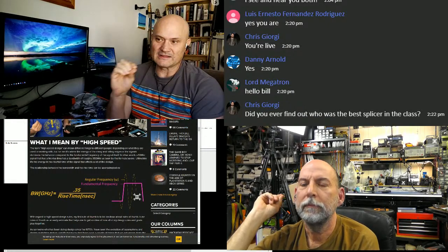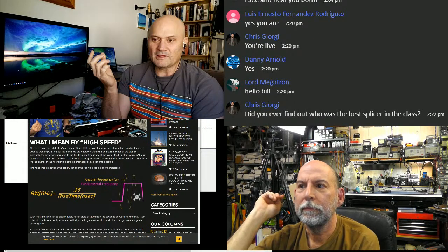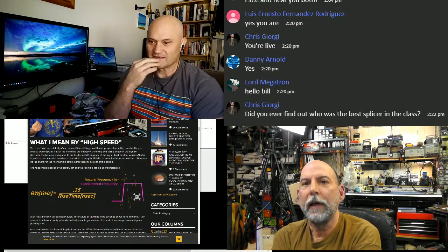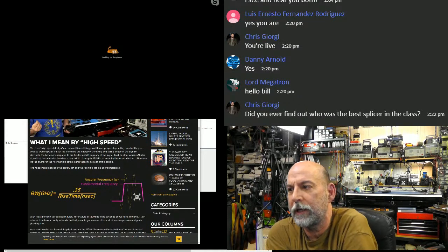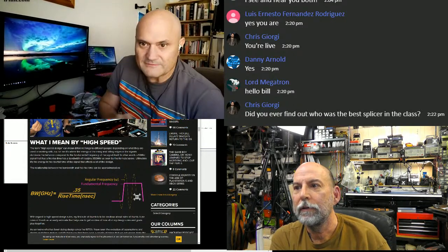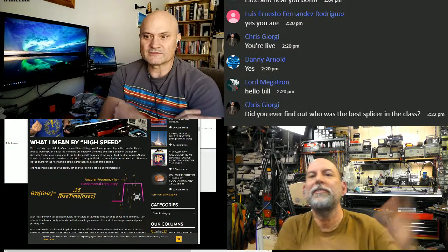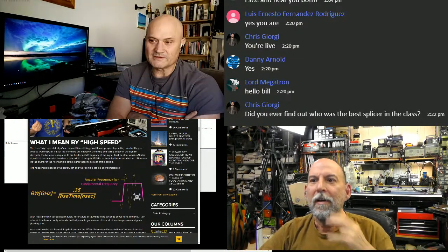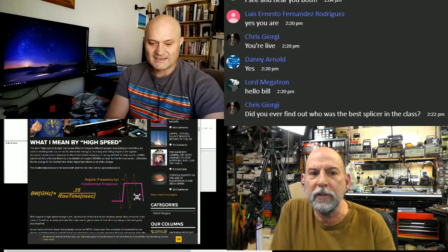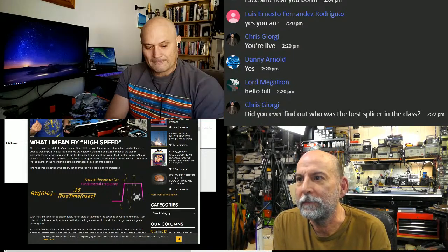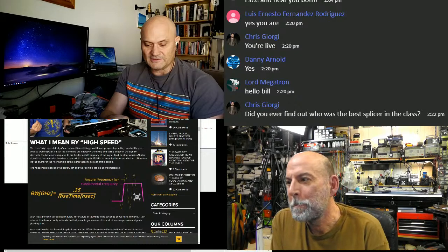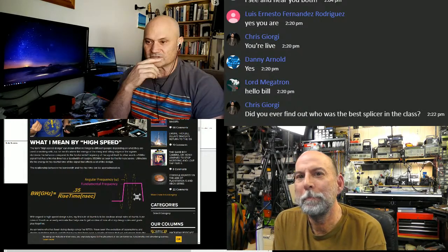And then with digital electronics designing PCBs, there was never any termination because we were going at low speeds, right? And lower power. And we didn't want to throw it away in a termination. And we loved CMOS because the inputs to all the gates were practically open circuit, so they didn't present any real load other than a little bit of capacitance. But they're bad then because they'll reflect the entire signal because they're high impedance. Right, and then the teachers at college said, well, we actually want that because that's what drives the voltage. That's what drives the voltage all the way up to VCC when a signal goes onto a digital net.